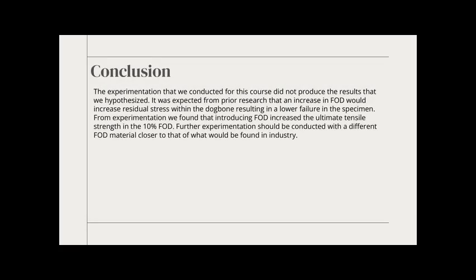The experimentation that we conducted for this course did not produce the results that we had hypothesized. It was expected from prior research that an increase in FOD would increase residual stress within the dog bones, resulting in a lower failure load in the specimen. But from experimentation, we found that introducing FOD actually increased the ultimate tensile strength at 10% FOD. Further experimentation should be conducted with a different FOD material closer to what you could find in industry, such as rocketry or other applications.